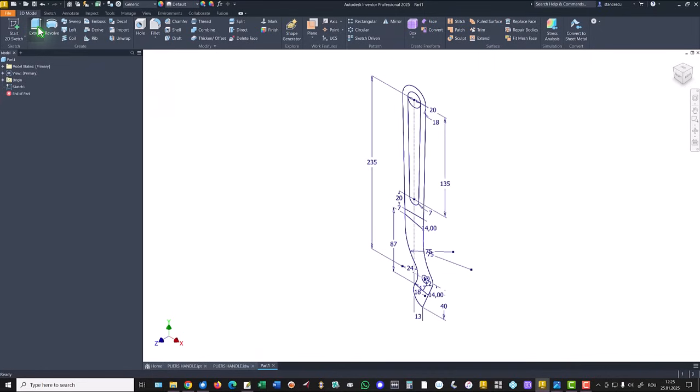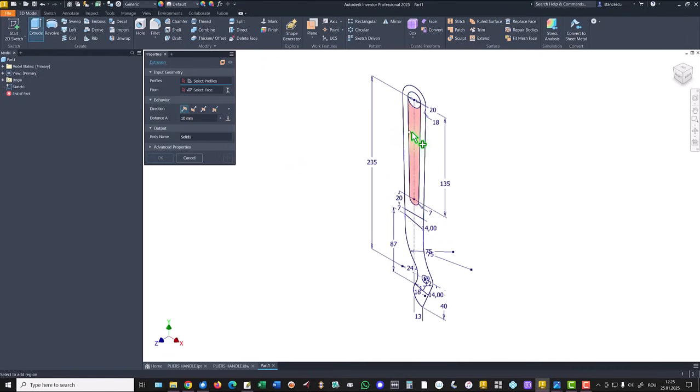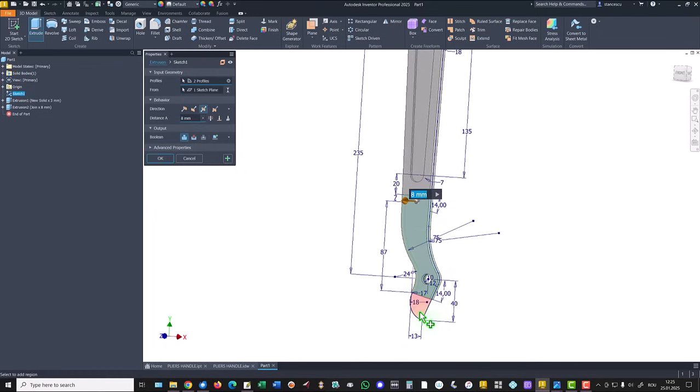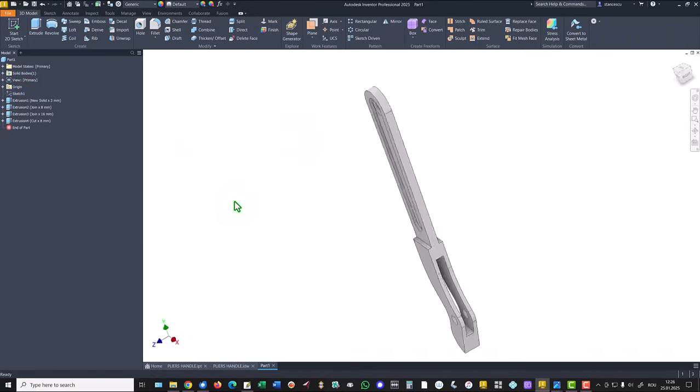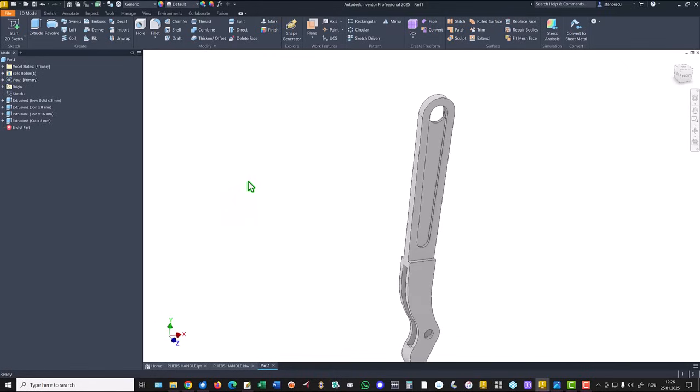Take a look here. Extrude this area symmetrical on 3, plus this other area symmetrical on 8, plus all these 3 areas 1, 2, 3 as 16, plus this only area with cut on 8. Okay, you see, all of them at once.